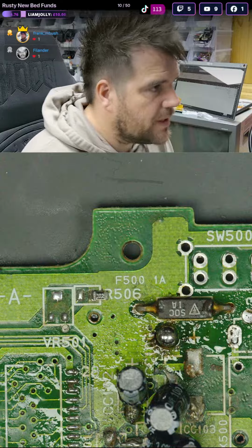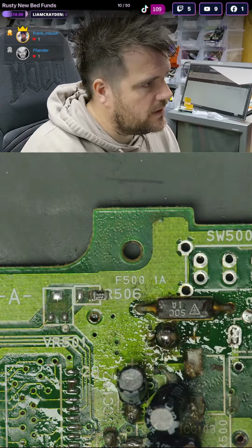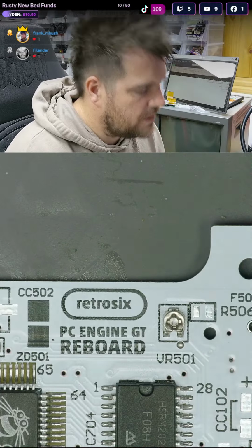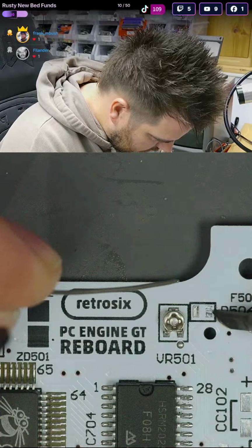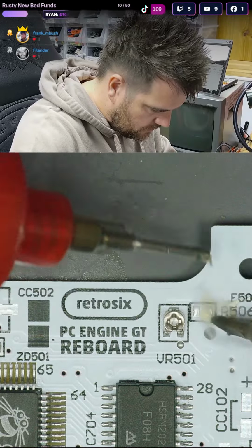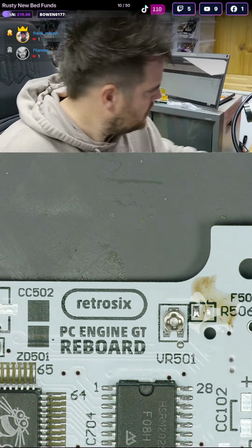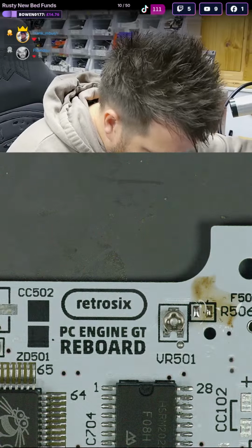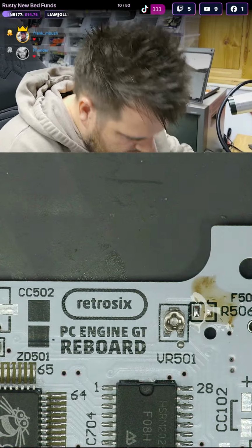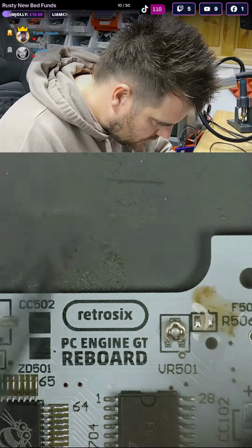This time, because this has already got solder on, I'm going to try and apply just a tiny smidgen of solder. We don't want too much on these pads, so that's probably easier said than done. There we go, a wafer thin amount of solder on there, and then when we move this resistor over, hopefully we don't have huge amounts of solder.